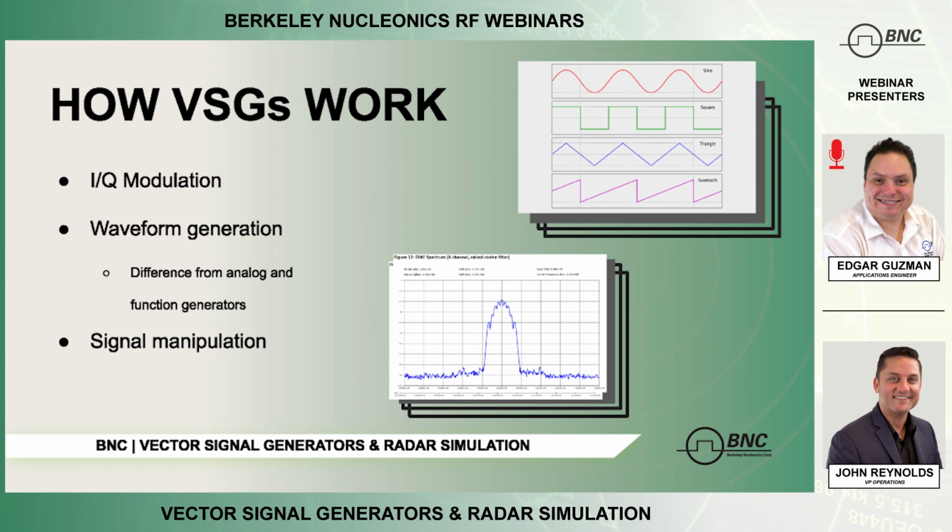If you change the amplitude of your cosine, the phase of your signal will shift, because it's adding them together. So you have two sine wave pulses, and when one gets larger, it's shifting the combined signal towards that way. And if you change the sine, it'll shift the other way. So that's how you can mimic, or actually create, a lot of the analog modulations using IQ modulation.